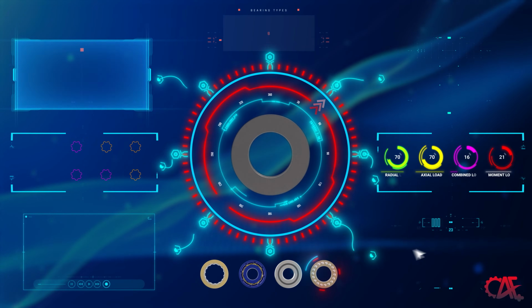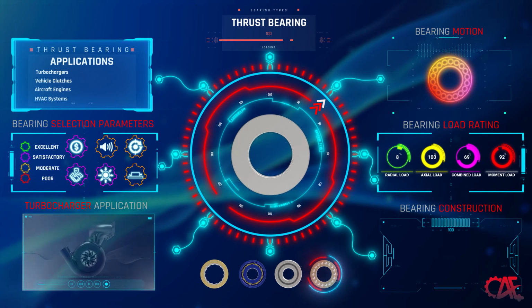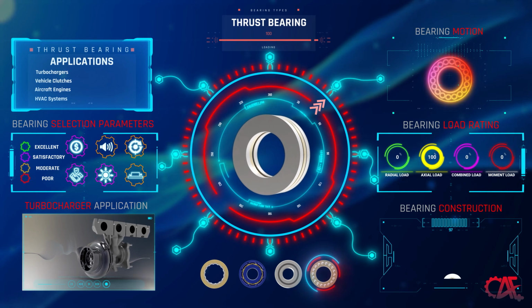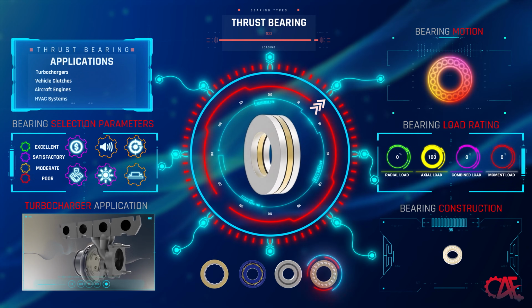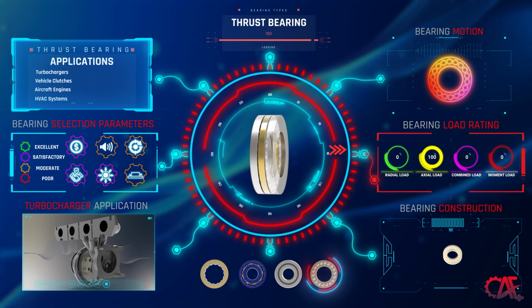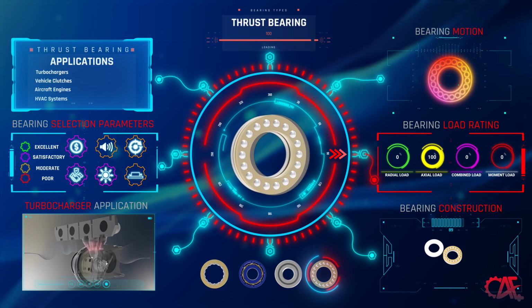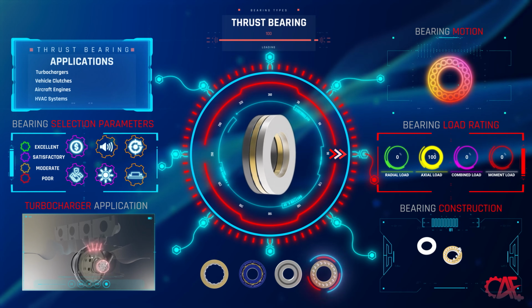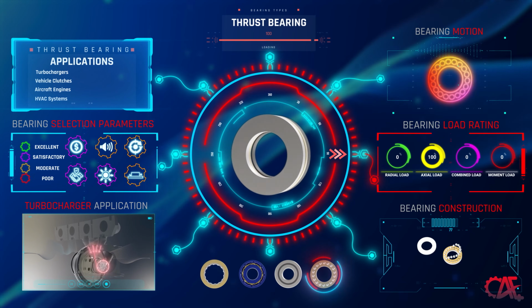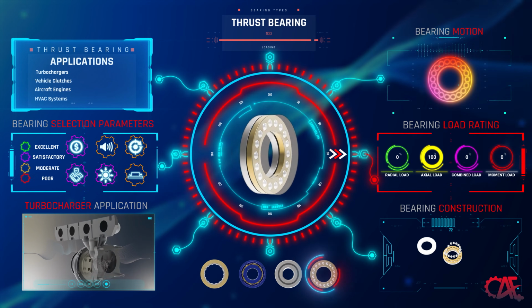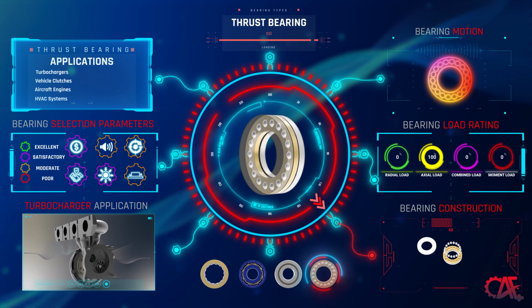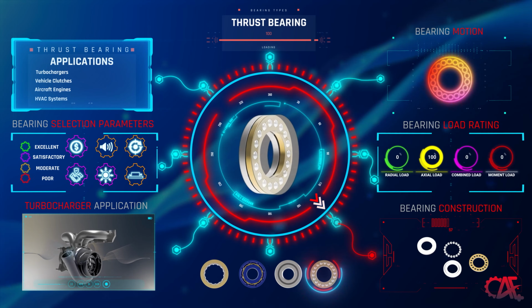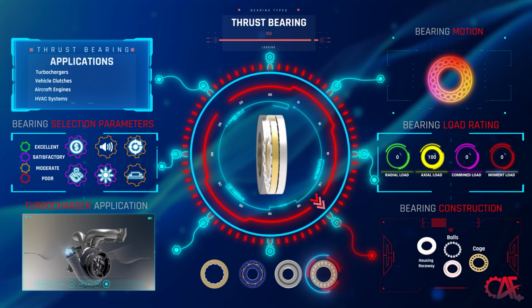Our last bearing comes with a unique design that can easily be distinguished from other bearings. Thrust roller bearings are a type of specialized bearing specifically engineered to withstand axial loads. The load performance chart of thrust bearings demonstrates their excellent to exemplary ability to handle axial loads. However, they are not intended for radial loads and are also not suitable for managing combined or moment load. They are composed of rolling elements, such as balls or cylindrical rollers, positioned between 2 flat raceway rings and a cage to hold rollers in line.